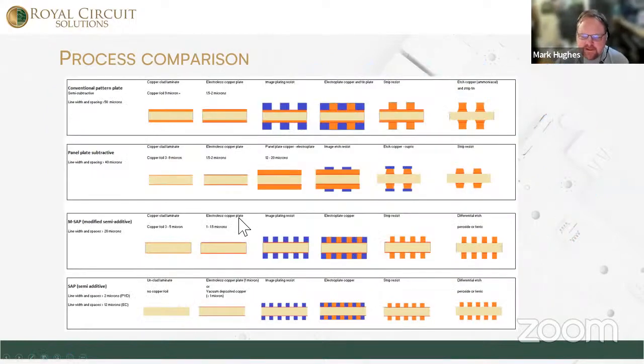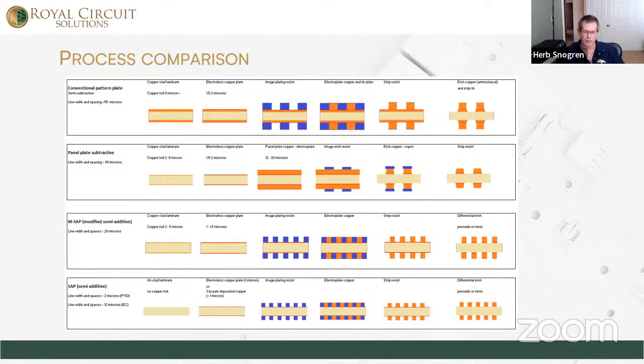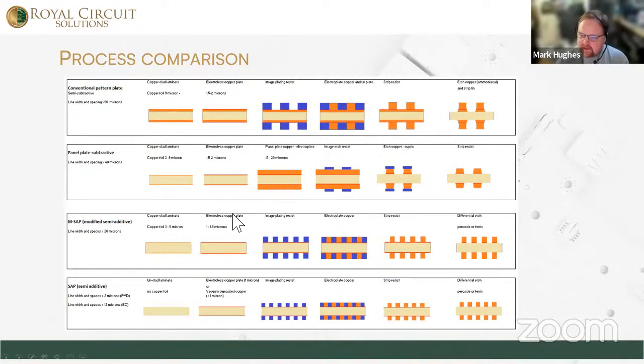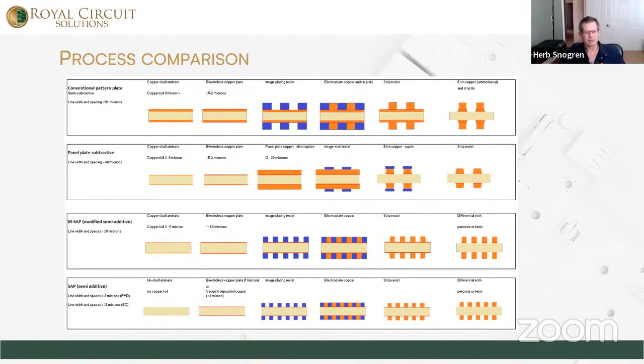How many lamination cycles can you do with this technology? Well, we're seeing a lot of stuff with 4 and 5 lamination cycles. So 4 stacked microvias is fairly typical. Okay, and that answers Eric's question: 4 and 5 lamination cycles. When you make these layers, and I apologize if this is a stupid question, I'm just not familiar with the technology, but are we doing cap or foil sequential construction on these things? It'll be sequential. So it's a build-up process.